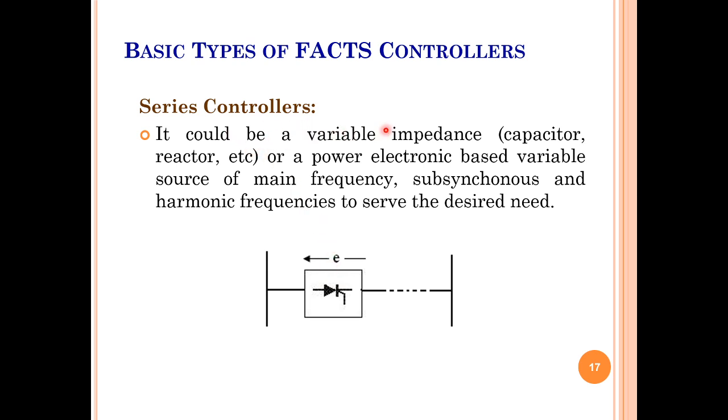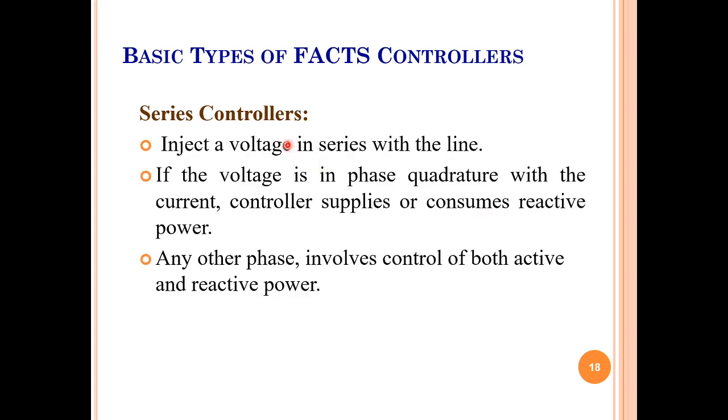Series controllers could be a variable impedance or power electronic based variable source of main frequencies, subsynchronous and harmonic frequencies to serve the desired need. These are the lines we have to remember. Series in the sense, in series connection, current is the same. I don't want to disturb that one. I would like to go for some other voltage, that is, inject a voltage in series with the line.